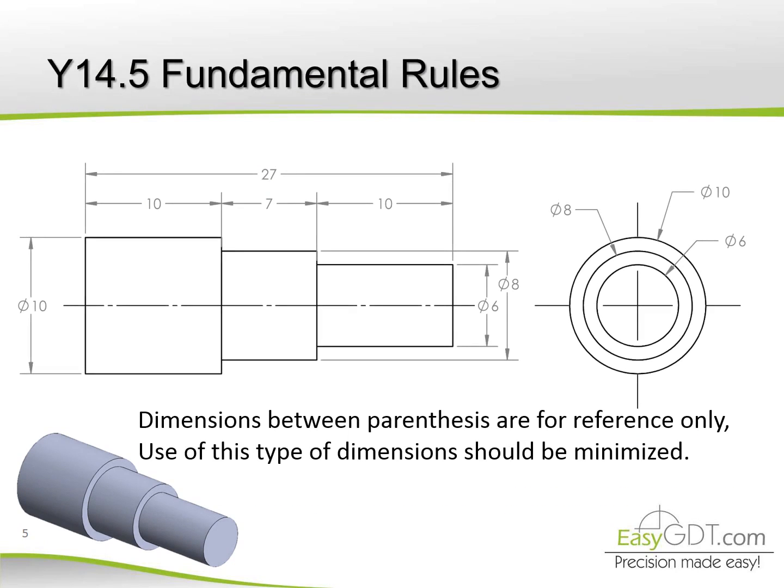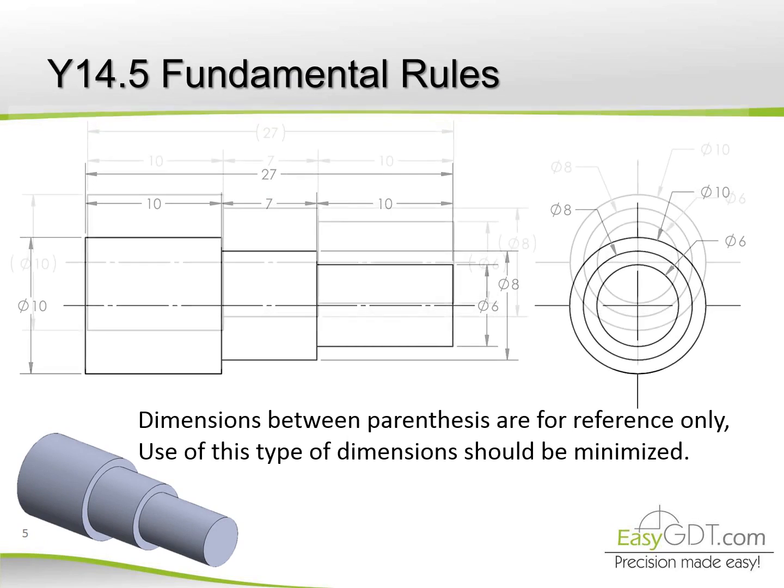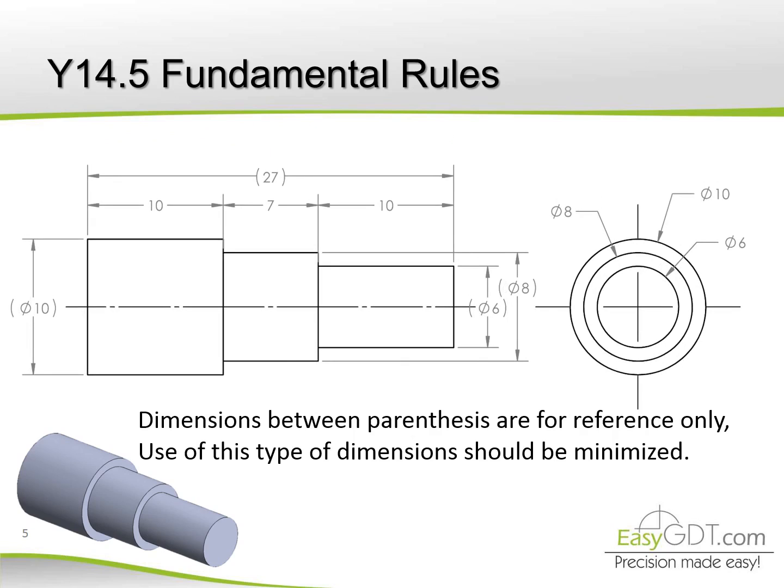We see the same part drawing, but now to avoid overdimensioning, we've set the repeated dimensions as reference by placing parentheses on them. Even so, putting too many dimensions causes confusion and sometimes reference dimensions are taken as official dimensions, therefore the use of reference dimensions should be minimized.